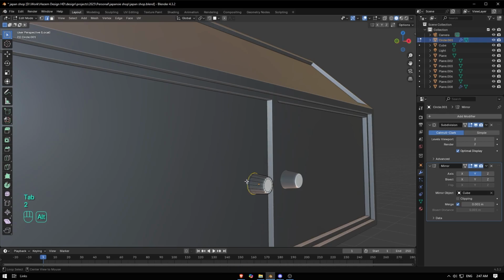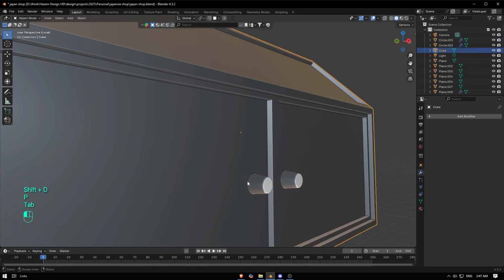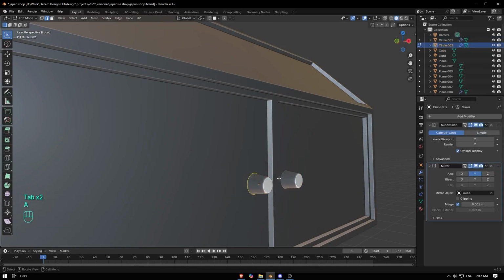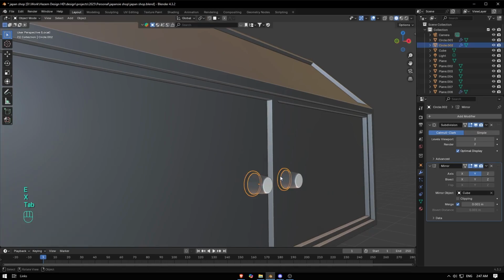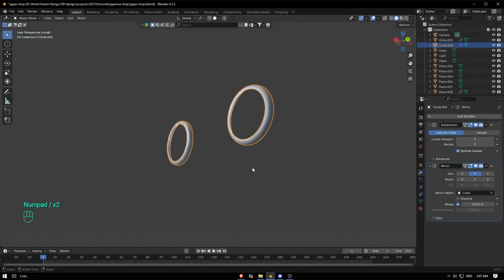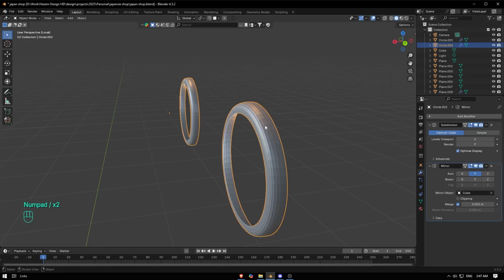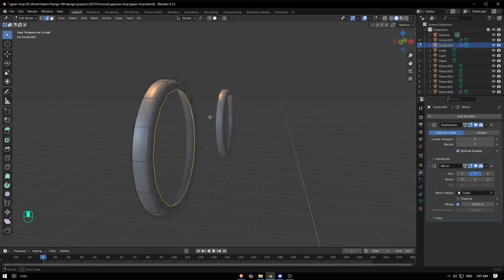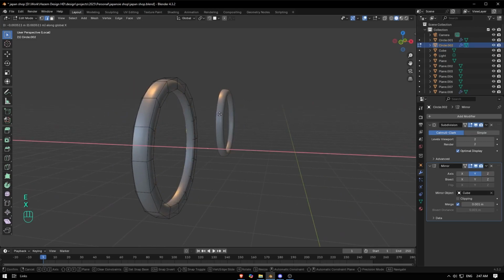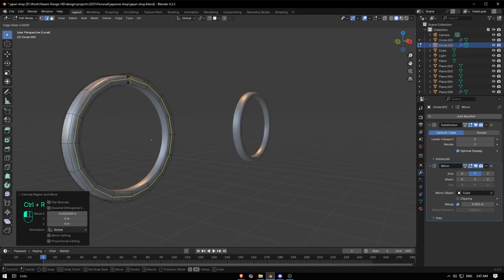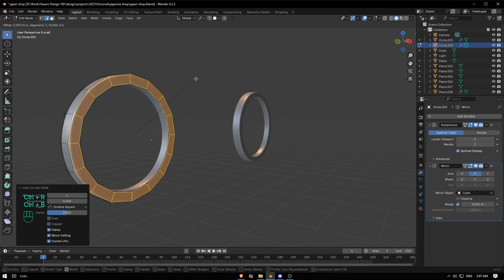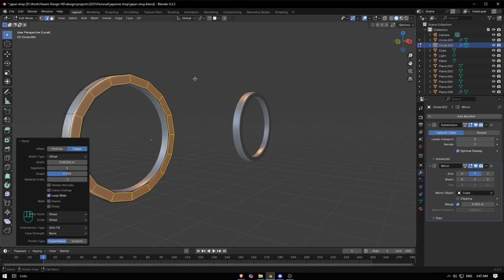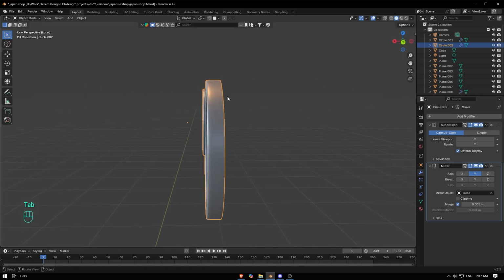I'm going to select this edge here, Shift D and B to separate. Select this one, yes, and then E to extrude like this, to make this ring here. Go slash, shade smooth, and go here, extrude inside like this. Add one loop cut in the middle and boost it like this one. And here I have a clean cut mesh.